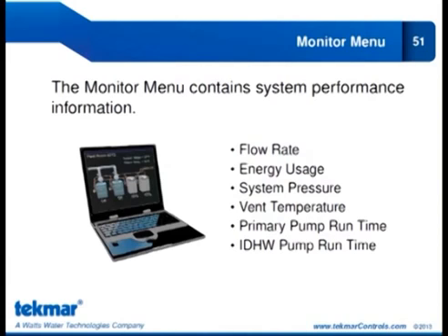And is that going to feed back some kind of pressure signal or what the flow rate is? Well, we will eventually support a flow meter. Right now, you can hook up an analog flow meter, and there are a few manufacturers out there, but the one we're probably going to support and supply as a Tekmar product is a Grundfos flow meter. We're looking to support flow rates anywhere from, say, 5 gallons up to, say, 400 gallons per minute. That flow meter will do a couple of things. One, of course, it'll measure and display the flow rate.